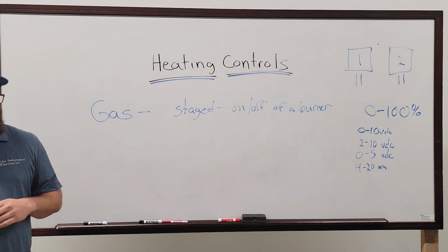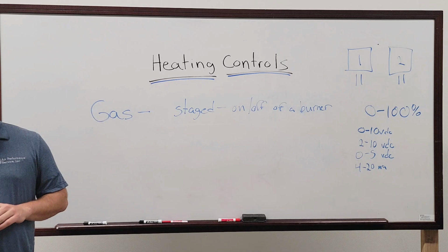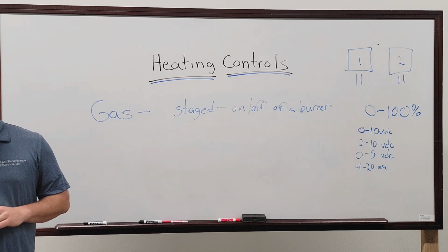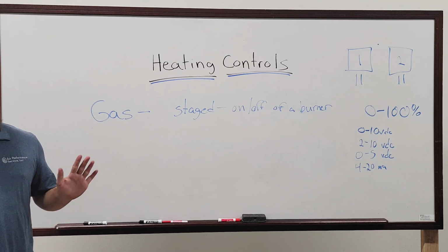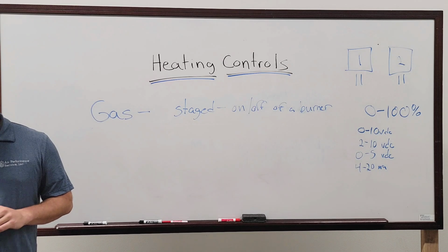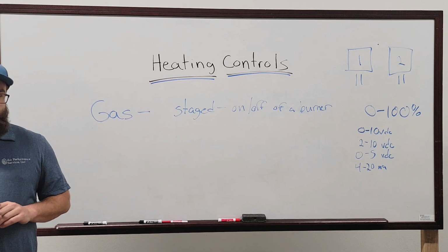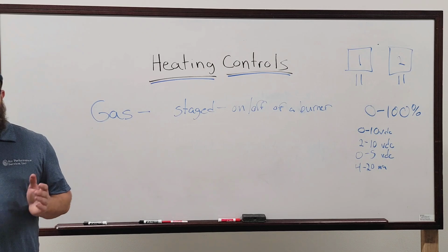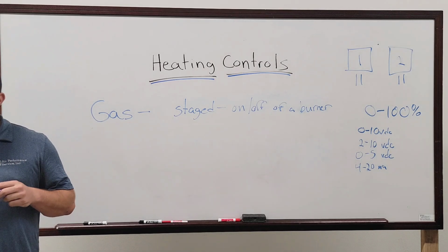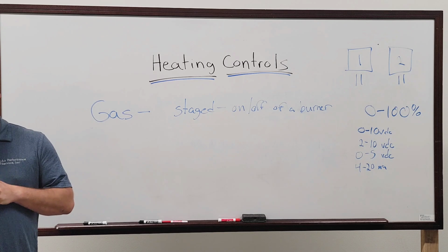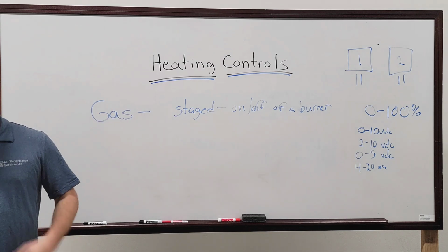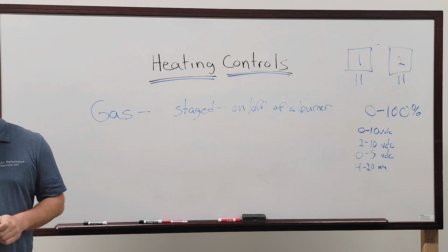Yeah, in all honesty, most of the time when you have those types of heaters, they're usually not even connected to the BAS. We do have some that are, I'm not saying they're not, but a lot of times they're standalone. Especially in the big flat fan systems, they would have those in the outside air chase to help warm up the air and keep the coils from freezing when everything was shut down. And just on wall stats, they're super simple, line voltage or whatever.